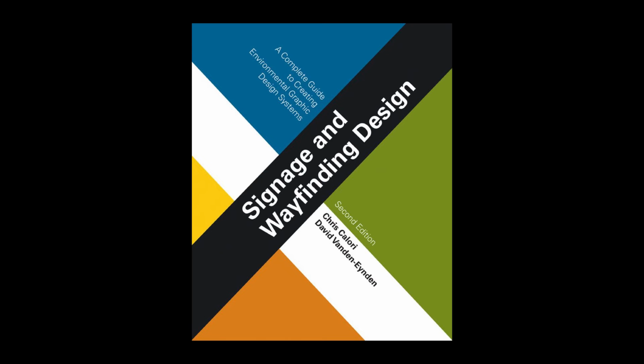Unlike adhesives, which form an effectively permanent bond, mechanical fasteners have the advantage of being removable, which allows access to the interior of sign units for servicing, such as to replace burned out lamps or to update directory listings. Fasteners are manufactured from a variety of metals, including stainless steel, galvanized steel, aluminum, brass, and chrome-plated brass. When attractiveness and corrosion resistance are considerations, stainless steel fasteners are often employed.